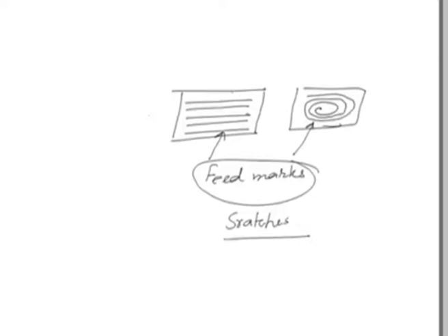However, this may not be desirable in most of the products. Therefore, how to remove these feed marks? The only way is to go for some of the finishing processes. Now, here is this AFM process, which can be effectively used for removing these feed marks, or at least to minimize these kinds of feed marks to a minimum or acceptable level. Let us see how it goes with the help of subsequent figures.